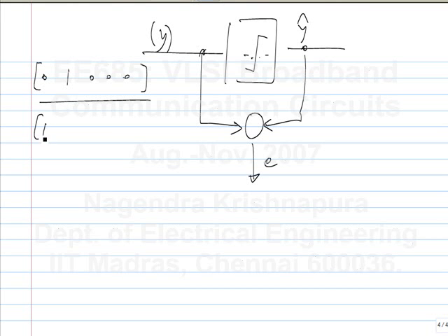Which one? This is, okay. Now, this could be that, depending on the initial condition, maybe this corresponds to, I chose this initial condition because I was imagining one precursor tap and 3 post-cursor taps. Now, if you design an equalizer with 4 post-cursor taps, you will in fact get different coefficients, right? Isn't it? That is probably what you are getting. So maybe what you are doing is equivalent to having no precursor and 4 post-cursor taps, if you do that.